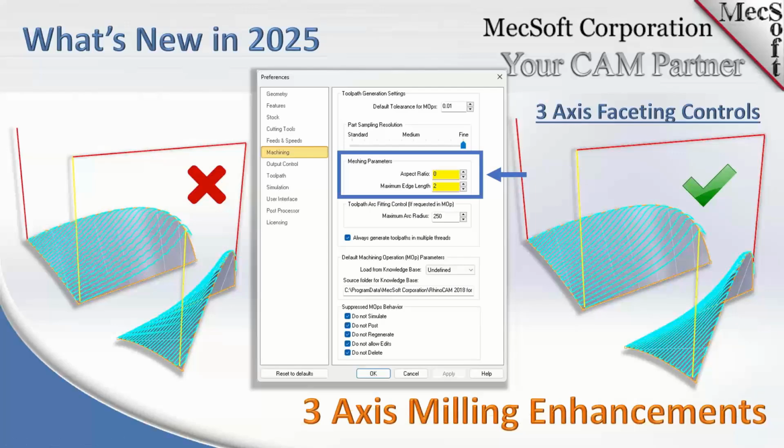One of the things that users can control now is the aspect ratio of the triangles in the mesh. Aspect ratio is basically the length divided by the width. So if you have an aspect ratio of 0, it's going to use the default mesh, whatever the default meshing was previously. But if you set the aspect ratio to 1, then the mesh triangles are going to be very regular, so the width is going to be the same as the height of the triangles in the mesh.